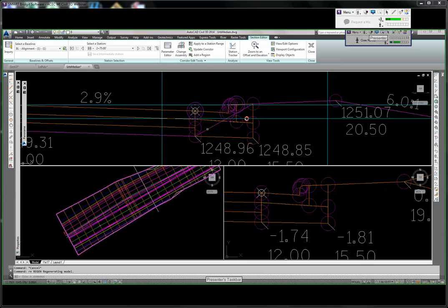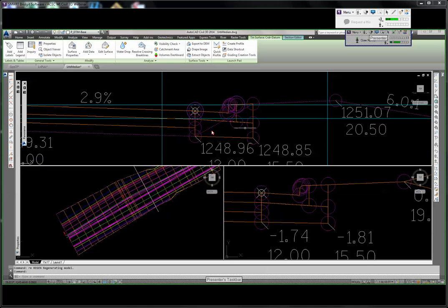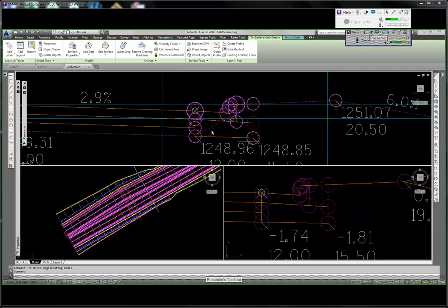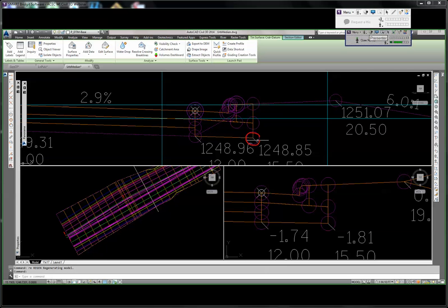Notice the surface, which is this purple line through here. In fact, I'll left click on it so it highlights a bit. That surface is coming down the bottom of our ground here. It's going from the crown subbase point over to the edge of travel way subbase point. Then it skips up to the back of the curb and gutter and continues on from there, completely skipping the subgrade point down here. The reason is that this point down here is directly beneath this point here. And surfaces do not like to go straight up and down and don't like to go backwards on themselves. So since it is perfectly vertical here, that causes it a problem. It can't see that particular line that's above it, or that point code.